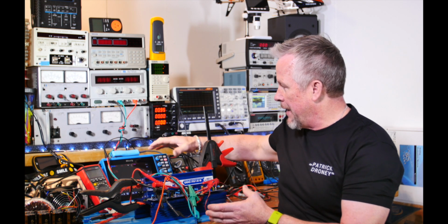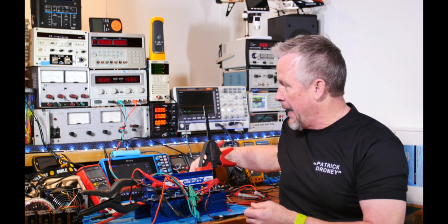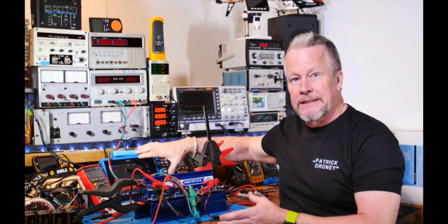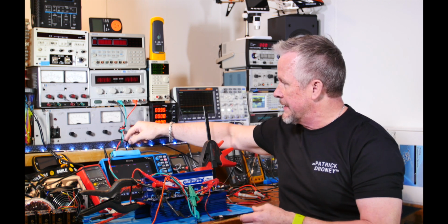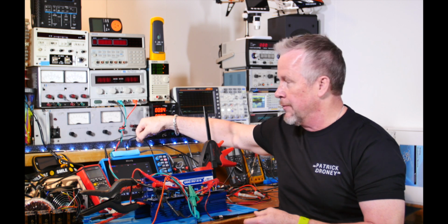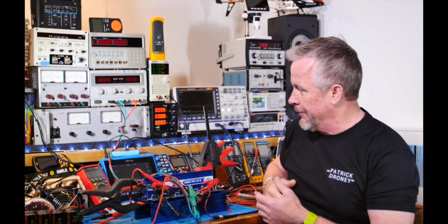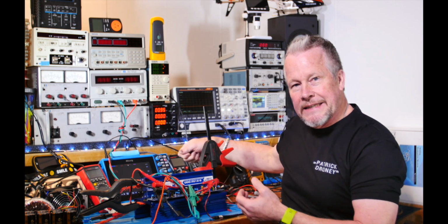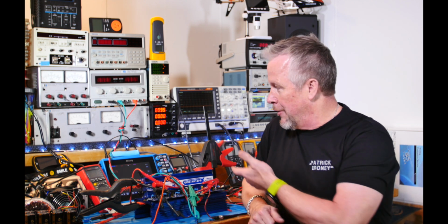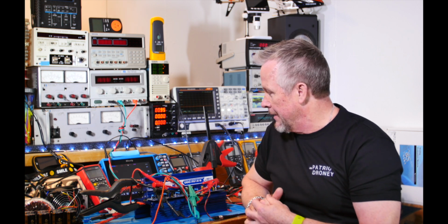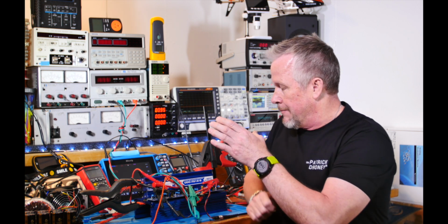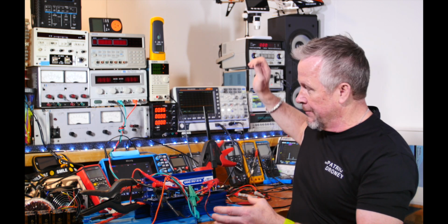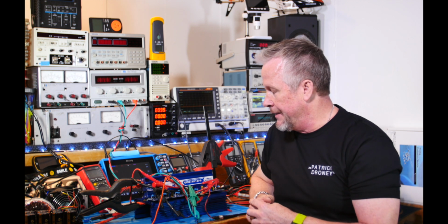And then as far as grounding, when I remove the external power source for the mixed sig, which isolates the scope, then the scope only gets its connection to ground from whatever the probes are connected to, and we only have a differential probe and a current probe. So by disconnecting that external power, I didn't see anything change there. So the circuit is grounded through chassis, through the generator, because that's tied to chassis.